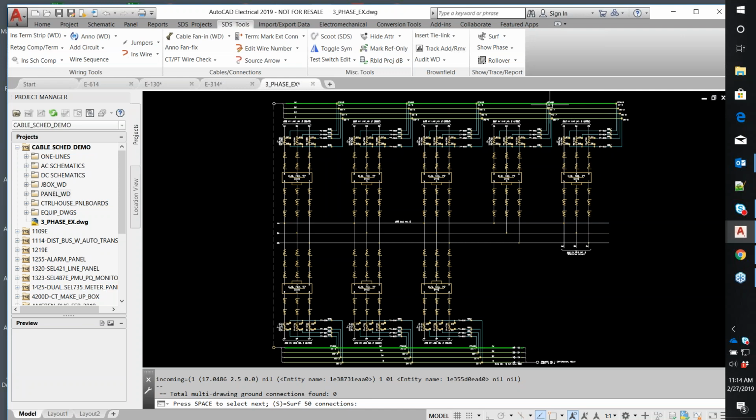You see it all lights up, so it's reading through the terminals, but it's also reading through a source destination. So you see it lit up down here as well. So it's showing you the phase, the wire I selected, it actually continues down here. Now, if I hit space bar, I can pick another wire, and it will do it again.